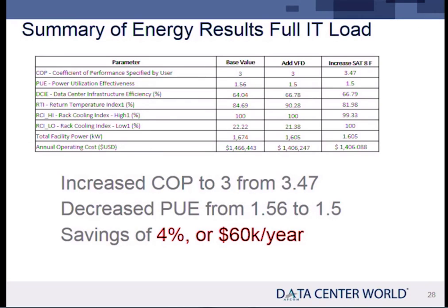However, hot aisle is a little tougher to implement in existing data centers because of cable trays and overhead stuff, and you've got fire marshals in there, so it's a little more difficult to do hot aisle containment from a practical point of view. People love doing cold aisle. But the cold aisle issue Jeff talks about is problematic. If you lose anything, you're literally cooked. You've got to start opening doors and stuff. I mean, you have to let bypass airflow go.